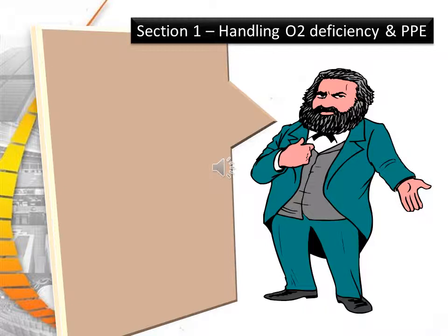Oxygen deficiency, as we just previously stated, only occurs in confined spaces, which many employers do not have. We mention it here because it does occur and can be deadly. Mental confusion can occur at about 16% oxygen, and workers will begin passing out below 10% oxygen. If oxygen drops below 8%, it can be immediately lethal. Supplied air respirators are required where oxygen is below 19.5%.